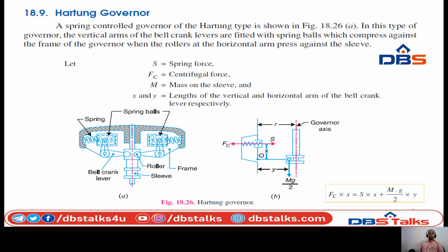Next, in the same way, we can solve it if the lengths of the two arms are not equal, and then we can find out in a different manner. After that, the concept is the Hartnell governor. In the types of governors, you know that it is a centrifugal governor model and it is a spring loaded type. This is called the concept of the Hartnell governor.